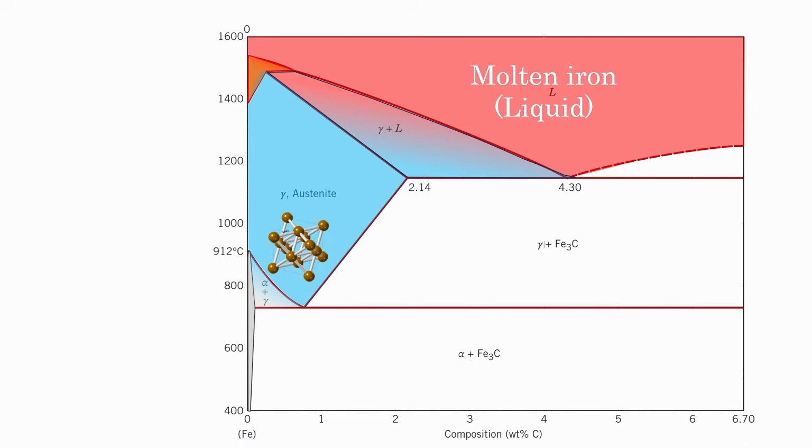And now let's understand how austenitic stainless steels 304 and 316 get their strength. First of all, these stainless steels contain only 0.08% carbon. With such a small amount of carbon, they cannot form any significant amount of cementite, iron carbide. Also, without enough carbon, martensite cannot form, so stainless steel cannot be hardened by quenching either. That means the strength and hardness of stainless steel is not coming from carbon. It must be coming from somewhere else.